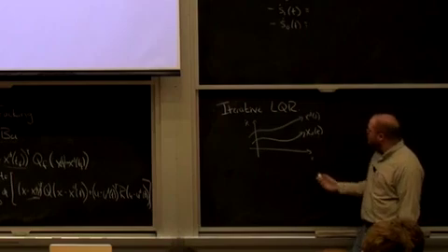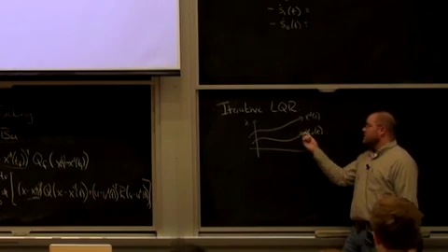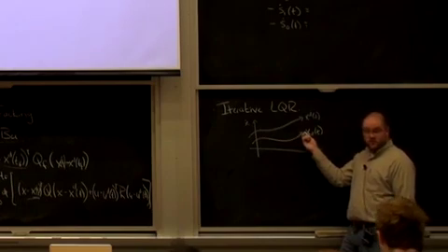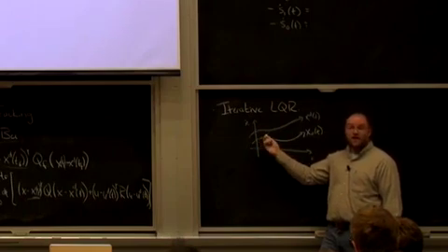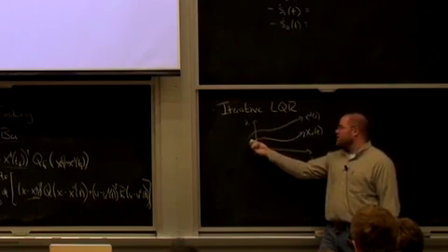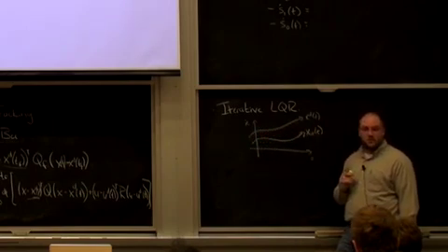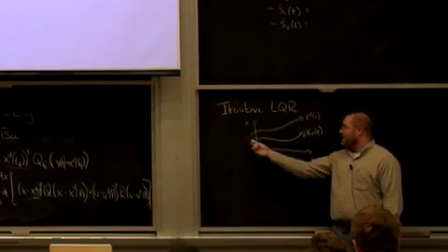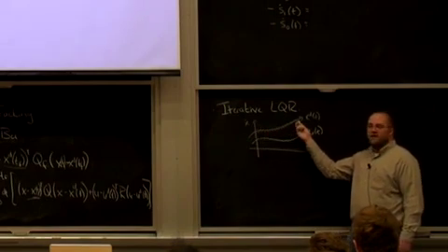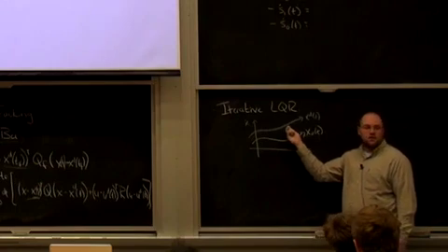Yeah. So here's one way to do it. Okay. Linearize my system around my initial guess, x0 of t. Then design a linear time varying optimal tracking controller, which tries to regulate my system as close as possible to that trajectory. Now what Steven said was exactly on point. If I drive my system away from where I linearized, there's no guarantee that my linear model was going to be any good here.